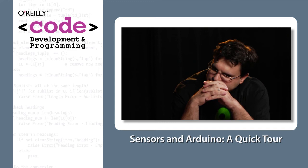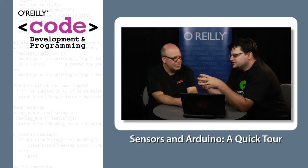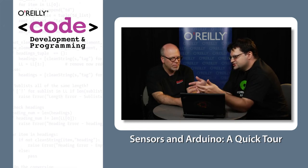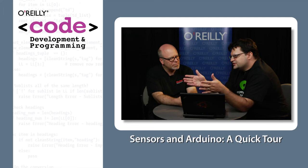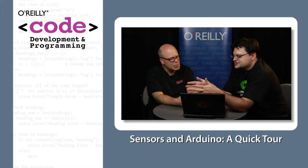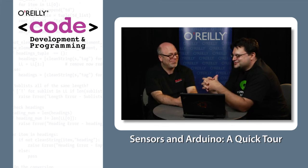It's got a tube. The Geiger counter is a steel or metal tube with an inert gas inside. Usually there is a window at one end made of mica, because it's neutral to the particles that we want to count. The gas is inert, but it's kept between very high voltage plates. In the specific case of the one I'm using, it's driven by USB. So getting 500 volts out of USB is a pretty cool thing. It's very low current, but very high voltage.